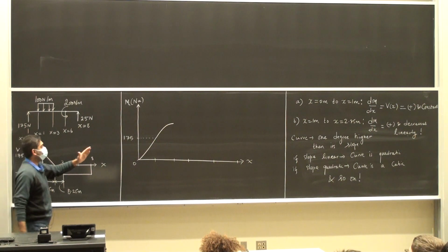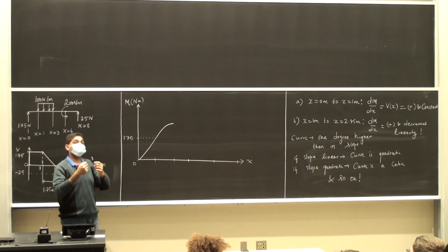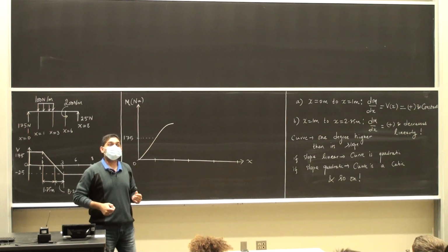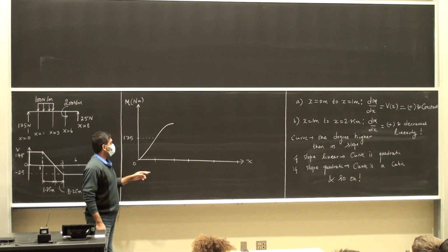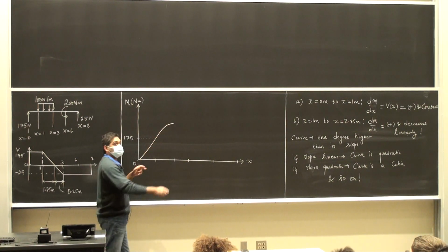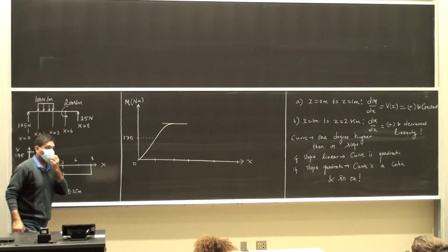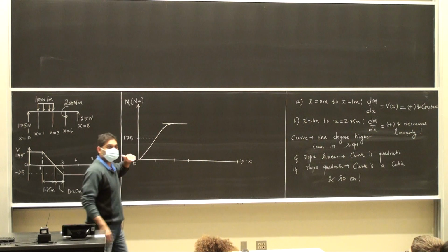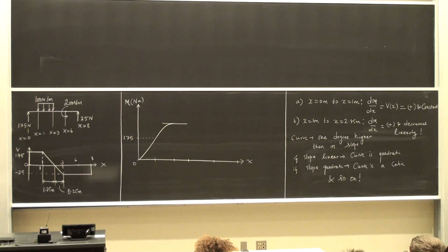Slope, what is slope? The slope here is the same, it has to be continuous. The bending moment curves are continuous except when you have a concentrated couple moment. That's where you see a discontinuity. Okay? I reach x is equal to 2.75 meters, my slope becomes 0, so if I draw a horizontal line, that tells me that the slope is 0. Okay? Question? Any questions?